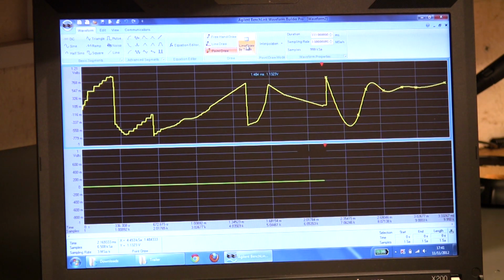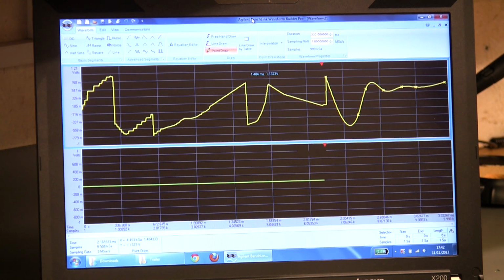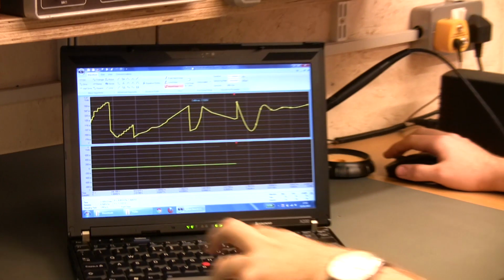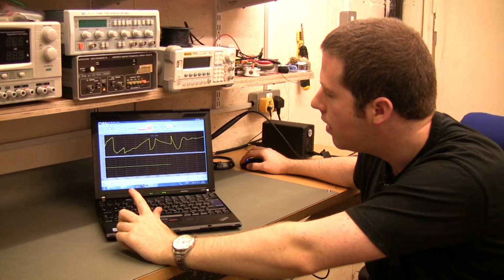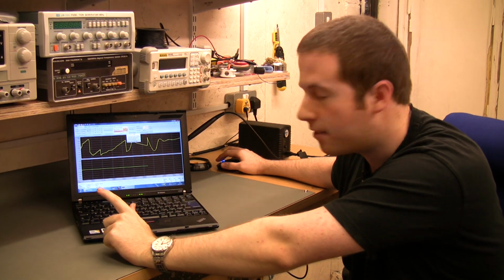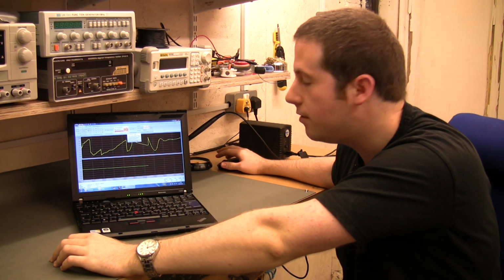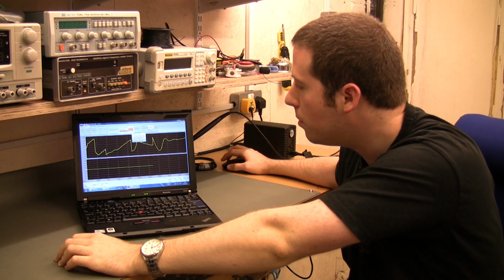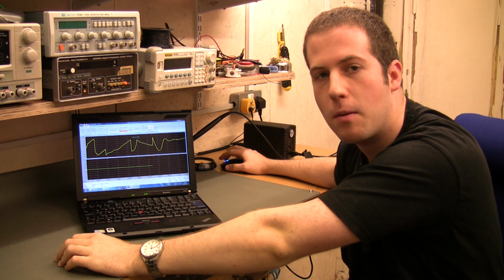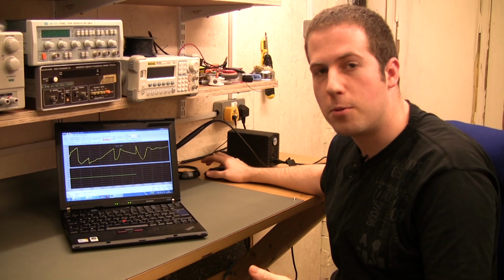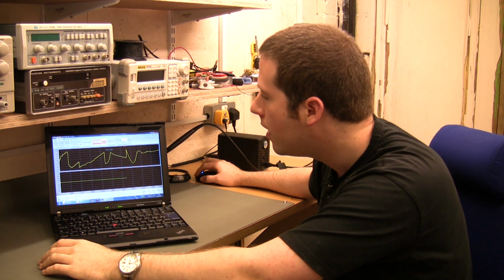And line draw by table. So let's say you've got LT Spice, you're using a piecewise linear voltage source, where that's literally you draw points and it joins them up with straight lines. You can take your exactly same waveform source, put it into this table, and your waveform generator will dutifully output exactly the same waveform. So if you want to prove your waveform is behaving the same as LT Spice as it is in real life, it's a fantastic tool.